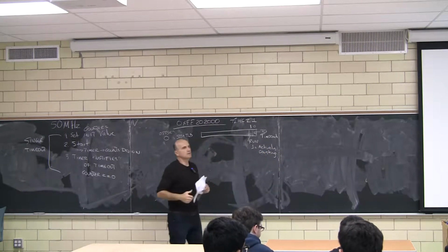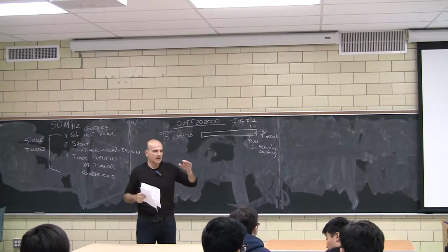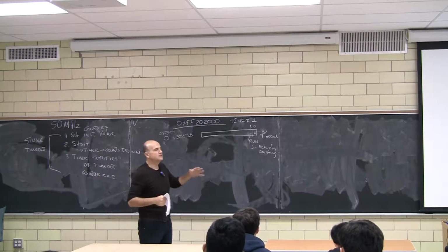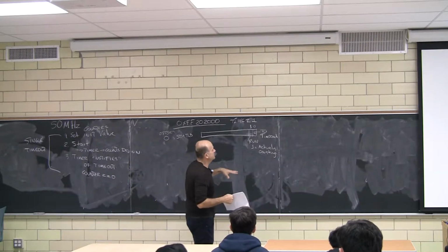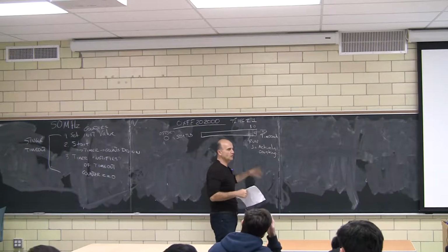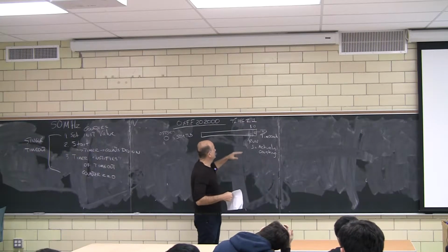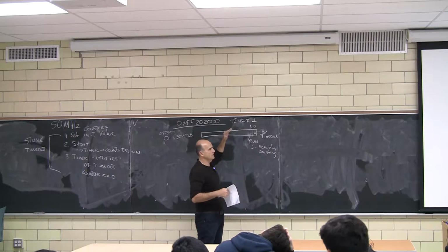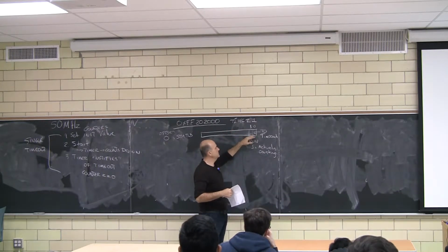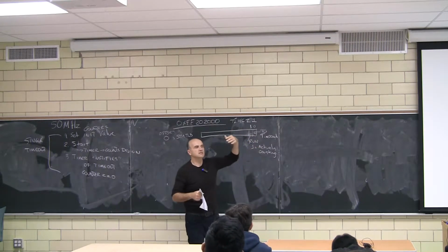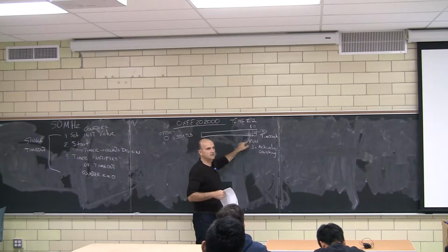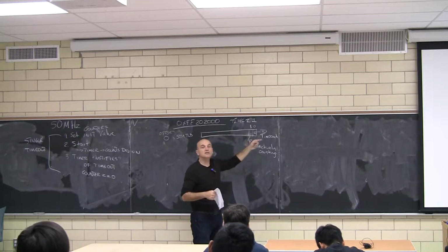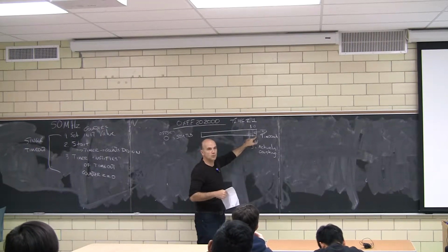Okay. All right. I just said a second ago that this is read-only. I was wrong. This is read-write. Okay. The mode of operation is as follows. In the beginning of time, this is 0. The moment you say start counting, this goes to 1, and this starts counting. The moment it reaches 0, this is set to 1.